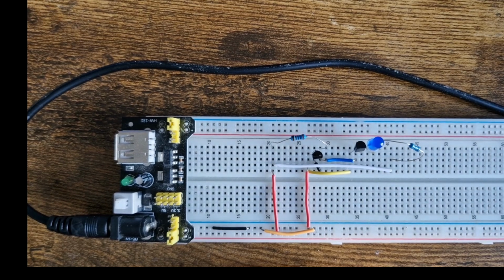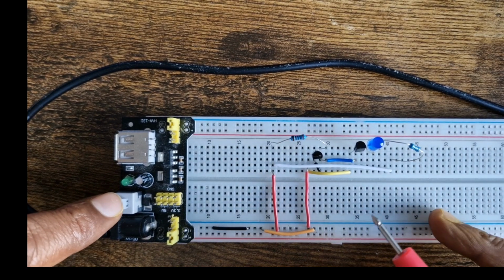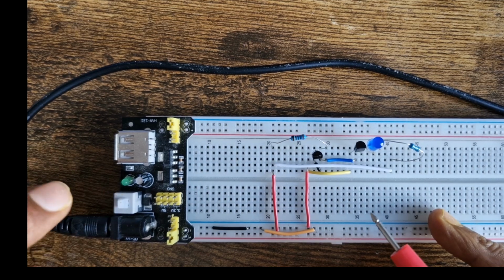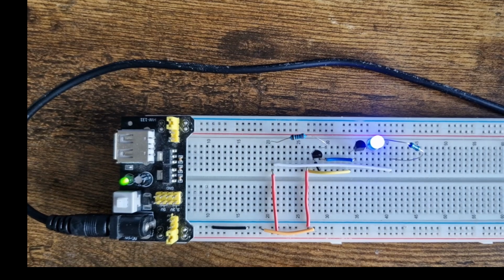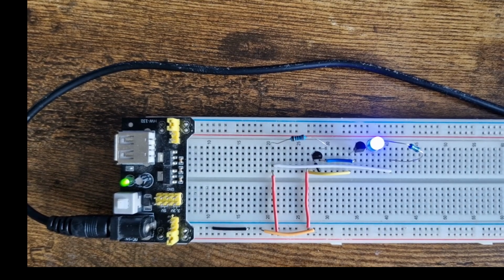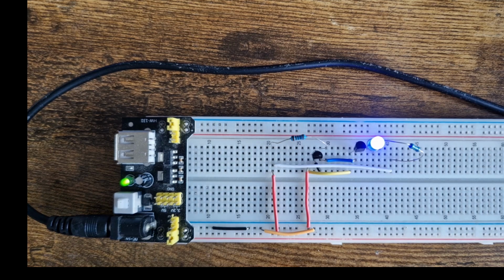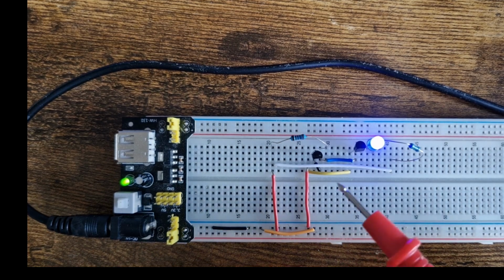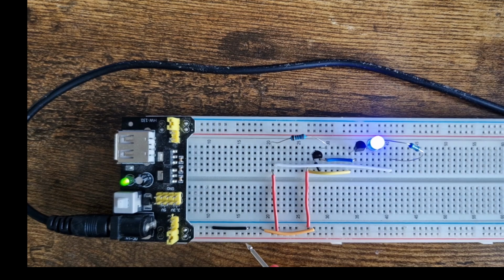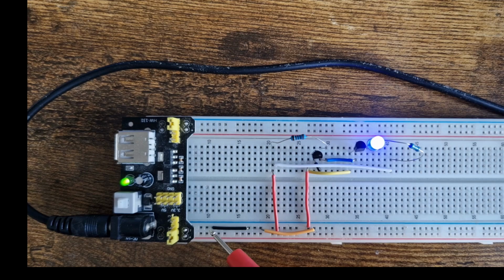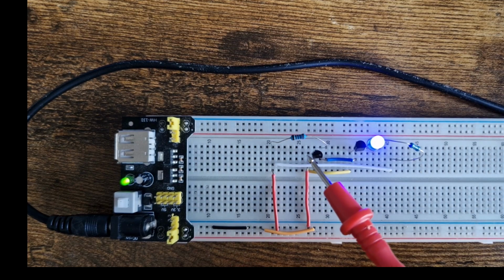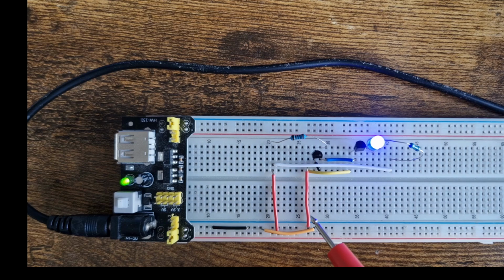Okay, so what you need to first do is press the switch here, and with this we will see how much current is generated. Here you see that the LED has been turned on and is glowing. It means the circuit is working, and what is expected is that the current would be around 2.5 milliampere, because we are sourcing a 5 volt DC supply, and as per Ohm's law, 5 volt divided by the value of the resistor sets the reference current into this part of the current mirror.